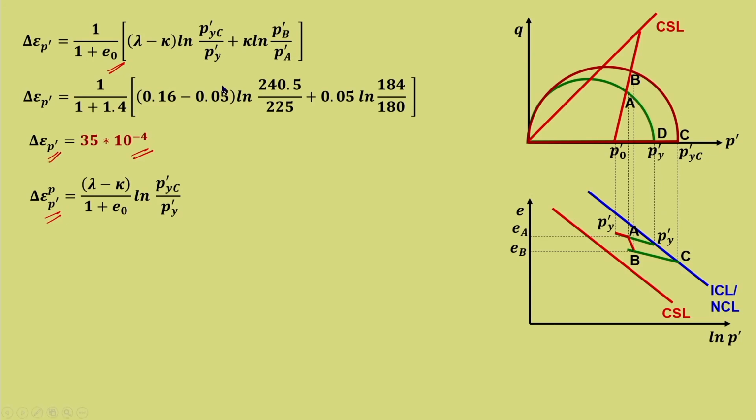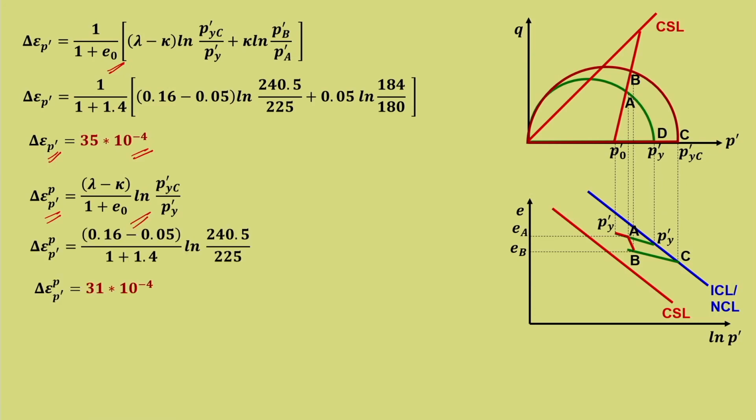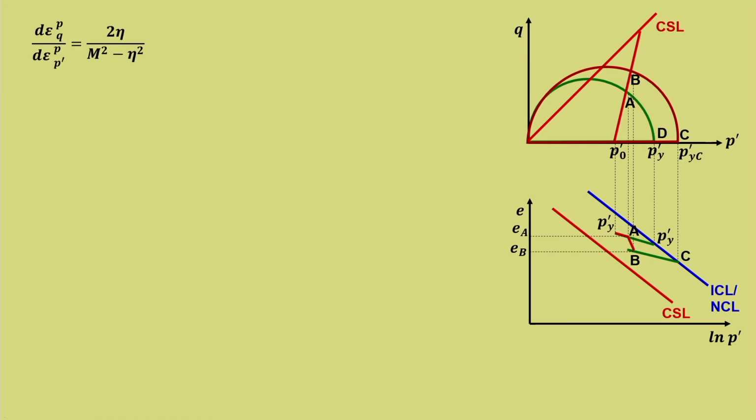That also we have, please refer back and you will see that we have obtained this expression. So, we just need to substitute it here, all the parameters are known. So, that will give epsilon P dash P is equal to 31 into 10 raised to minus 4. Please substitute and you can see for yourself. So, we have determined the total volumetric strain for the incremental portion. Knowing that, we have determined what is the plastic volumetric strain for the incremental portion.